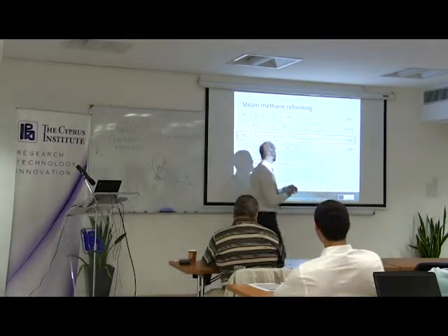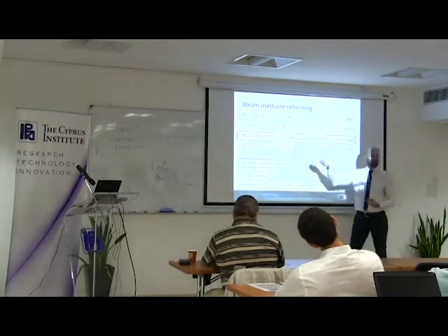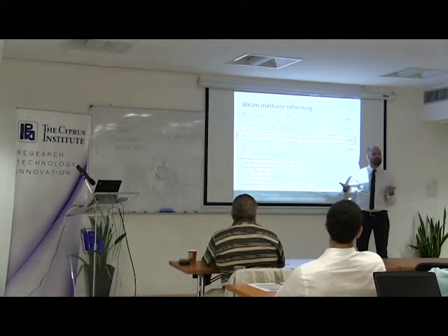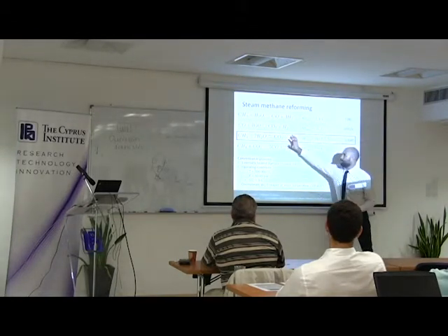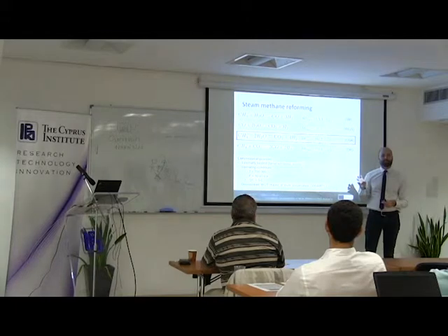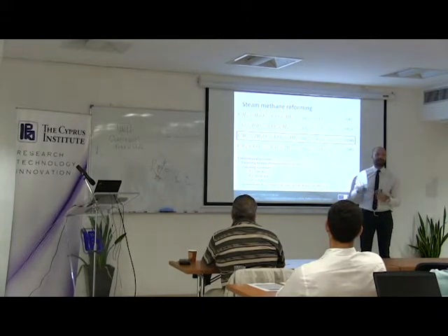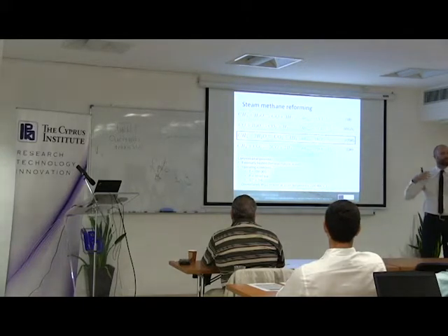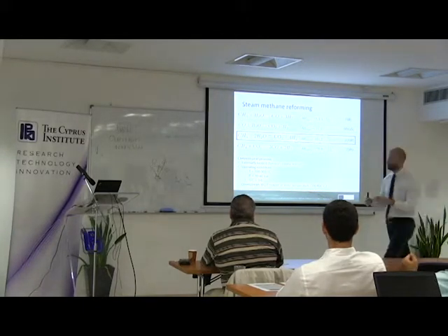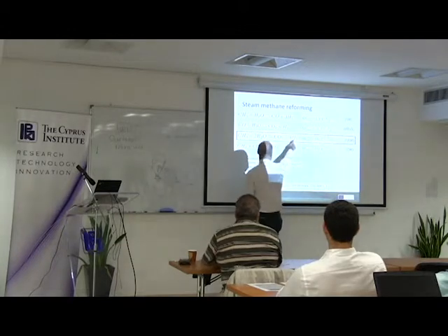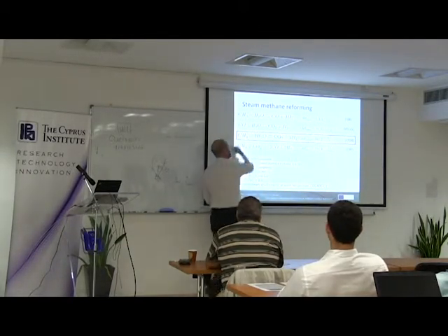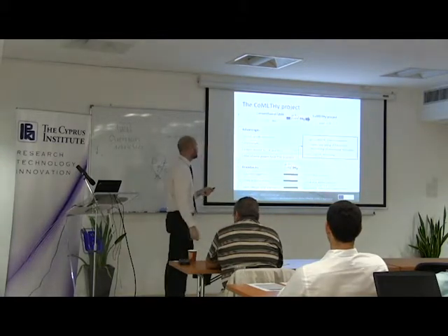But if you continuously withdraw one of the products from the mixture, this equilibrium will never be reached. So if we manage to remove hydrogen as it is produced within the reactor, the temperature won't be a problem from the thermodynamic point of view. I will push the reaction, it will continue. Because if I remove hydrogen, it won't be available to react with CO2 and produce the reactant again.